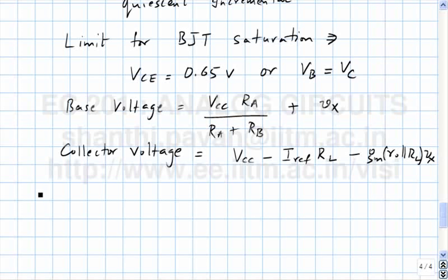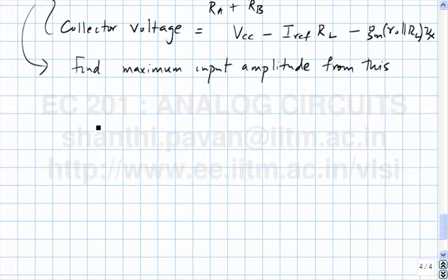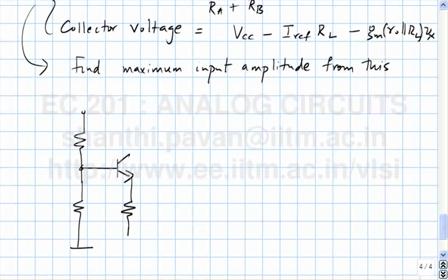And from these two you should be able to, what did we say when we were discussing the common source amplifier where we had this current source in the source? We said that in many practical situations, especially in discrete circuit design, it's not possible to get current sources. So what do we do? What's a poor man's current source? A large resistor. So this is now a very commonly used bipolar technique. I'm not going to go through how we jumped from the current source to the resistor all over again.